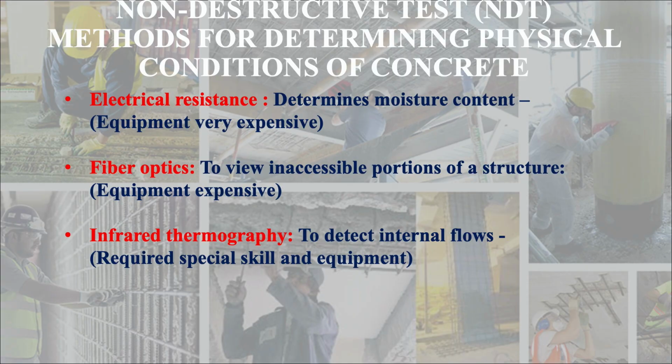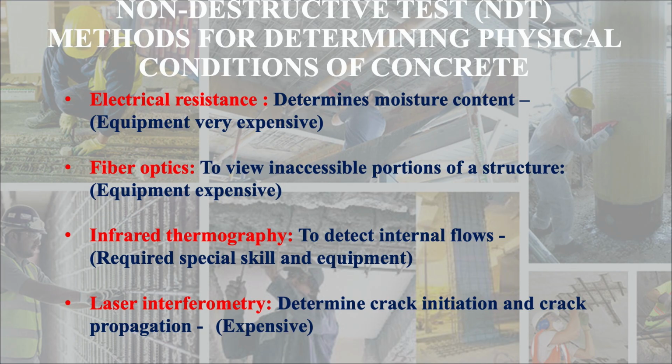Then another test is infrared thermography. Using this test you can detect internal flaws, but here you require special skill and special equipment. Then another way is laser interferometry. This is used to determine crack initiation and crack propagation. This method is also expensive.